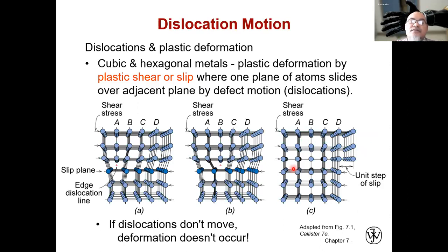So dislocation motion and plastic deformation are very much related. When we look from an external point of view, from the macro scale, when a material deforms, like we mentioned metal, when metal is bent and deforms, what happens is that some dislocation within that metallic structure is moved, maybe from the middle, until it goes to the edge of the material, such that the deformation can be seen from outside, at the macroscale.